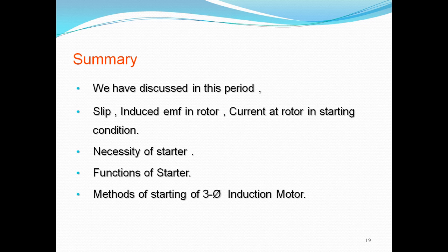So this method is used only for slip ring motors. It is not used for squirrel cage rotors. For squirrel cage rotors, we will use star delta starter, DOL starter, and auto transformer starter.